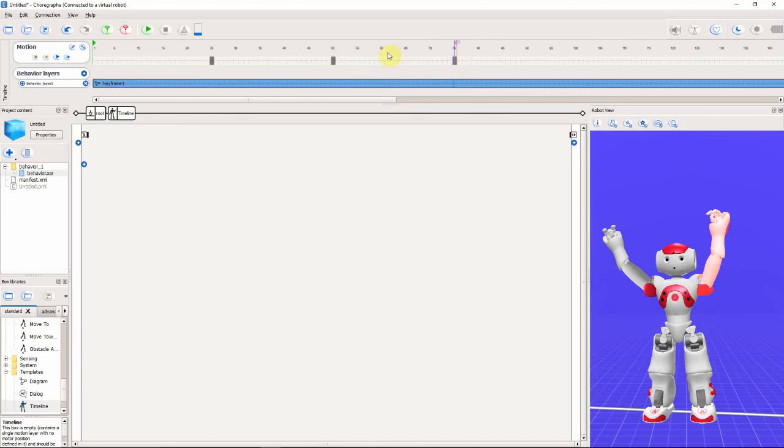The relative spacing between these keyframes we've created change the rate at which the robot moves. So if I want that last arm to go up much faster, I drag it closer to the previous frame. And I'm going to sample that animation again. Notice the left arm of the robot went up much faster because of the relative spacing in our timeline.